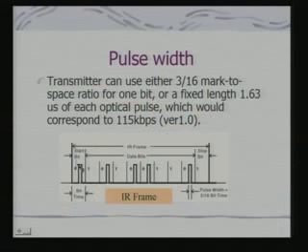So you have a start bit, which indicates the beginning of a data transmission, followed by the data bits, and then a stop bit. These pulse widths are typically 3/16 of the bit time. So it is not that corresponding to the bit, it will always be on.